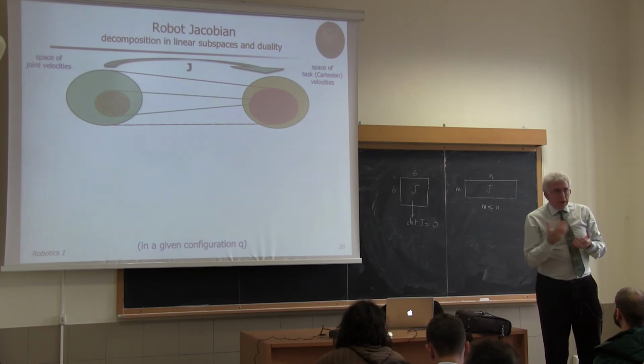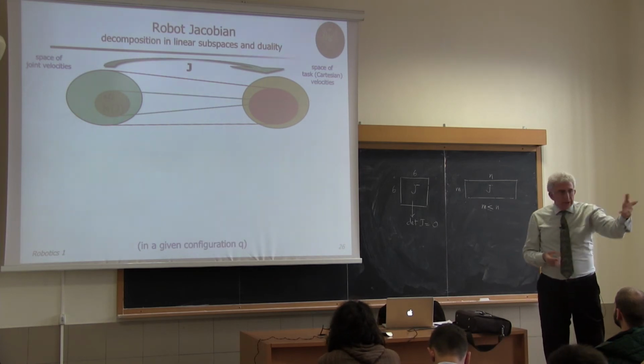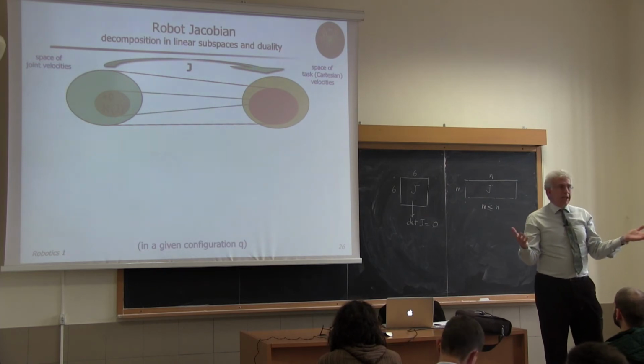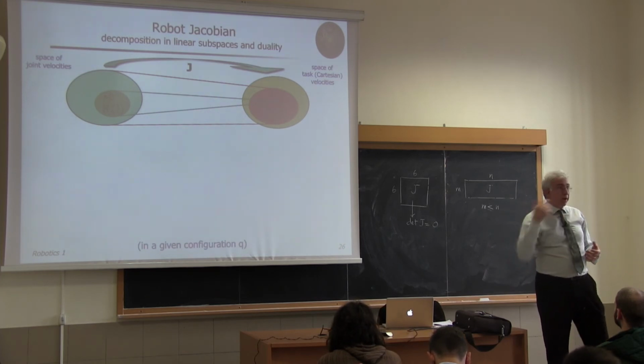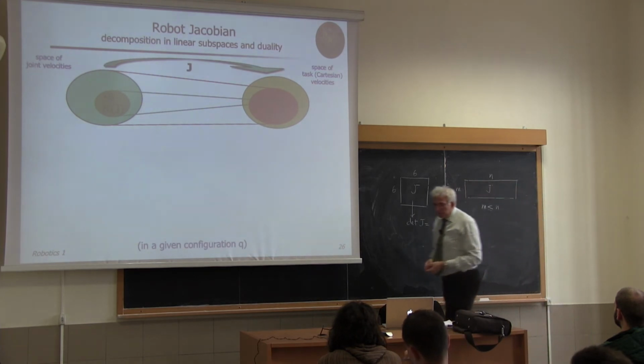And in fact, this problem becomes essential when you're specifying the task in the Cartesian space. You say, okay, you're there. Now you have to move in this direction. Oh, this is not in the direction of the range in this configuration, so I cannot achieve this. No matter how fast or how combined my joint motion, I will never achieve this.